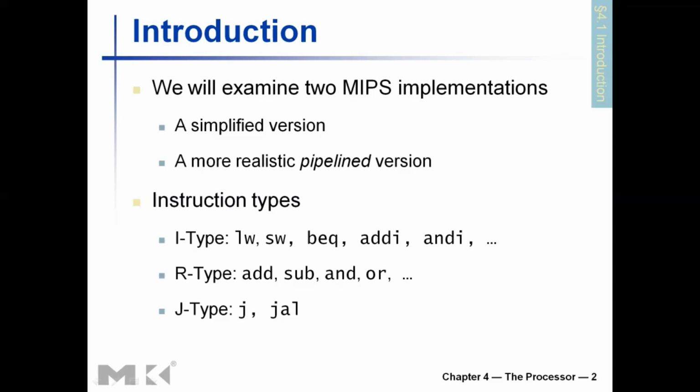So in I type instructions, there is one immediate operand given in the instruction itself. And there may be flow control, data processing, data transfer, all kinds of different instructions under that same category, I type. Then in R type instructions, the instruction contains all register addresses, not offsets, all register numbers.